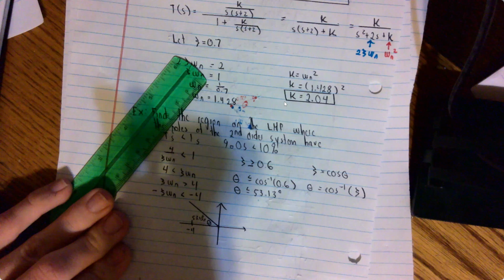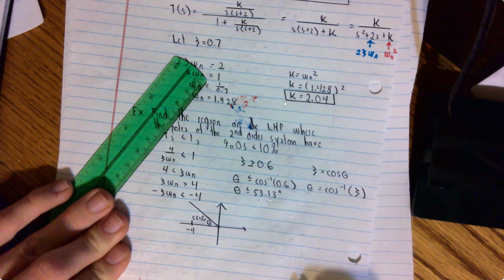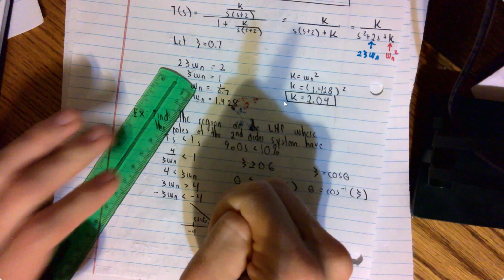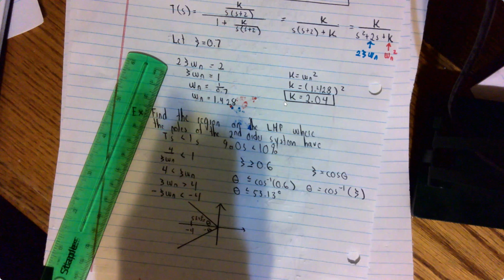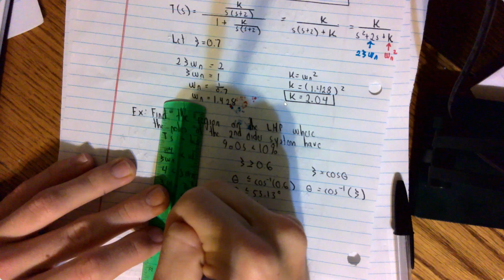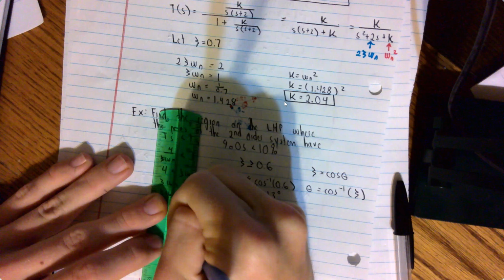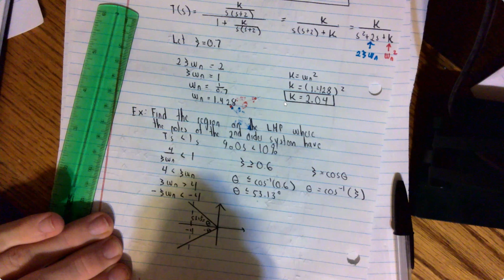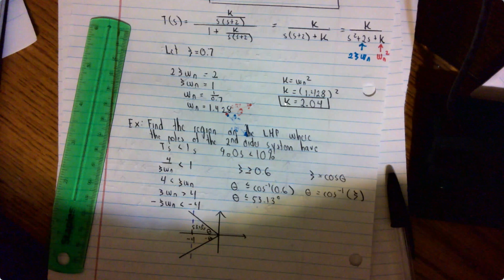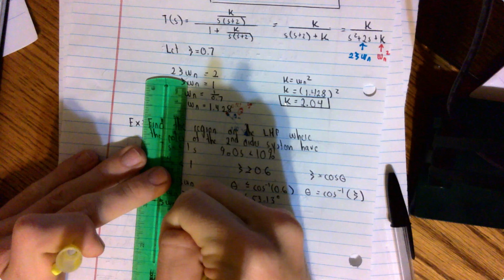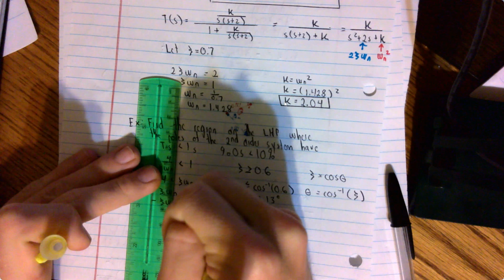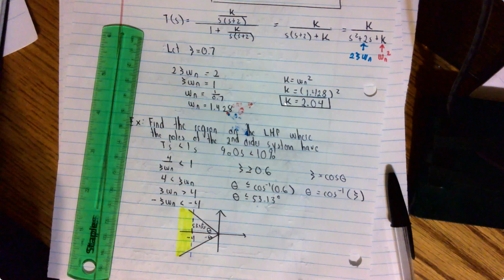And so recall that if you have conjugate poles, it will be on the opposite side as well. So that's why we have to draw it. Also negative theta, so negative 53.13 degrees. And so this -4 restricts it that it must be past this point right here, not including, and it must fall within this region of the angle. And so your poles can be anywhere such that they fall beyond the -4 and they fall within the 53.13 degrees. And so that's how you would find it.